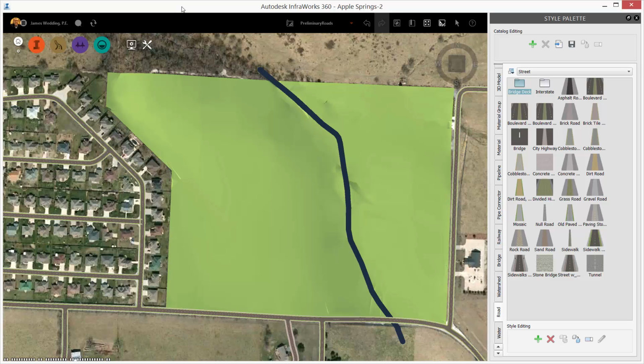I'll use the road design tools to lay out roads in both horizontal and vertical, adhering to engineering standards, and then use the analysis tools to check for rough lot spacing, and I'll also create a road style that helps me get an approximation for the lot count.